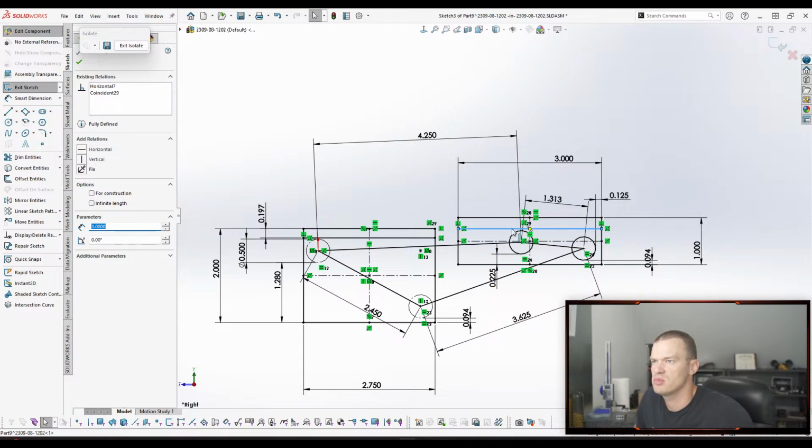And when you're drawing your sketches, SolidWorks will try to help by putting in relationships to things, right? And when the sketch is simple, like if you're just doing a circle or a square or whatever, it's not the end of the world. But when you're doing top-down modeling, you're putting a lot of information inside of sketches sometimes. And so you have to be careful when you draw geometry to really pay attention. This was an obvious one because I drew a line and it was fully defined, right? I hadn't dimensioned where that line should be, and so it was easy to pick up.